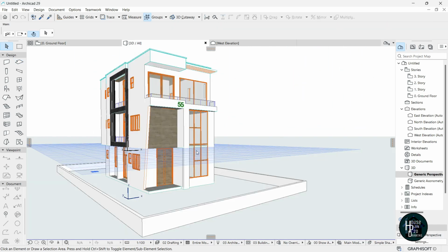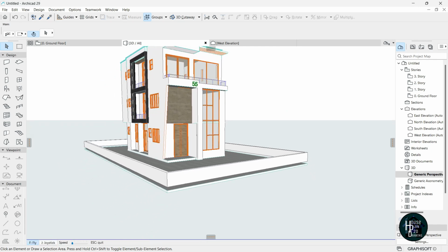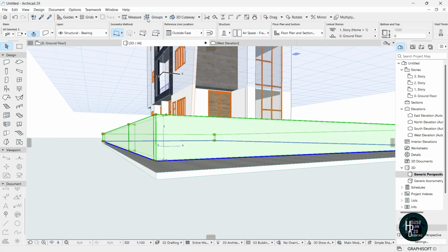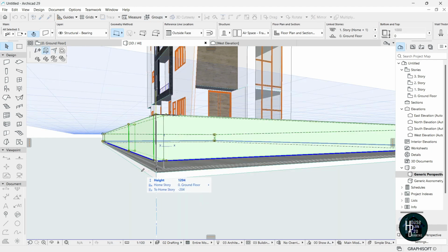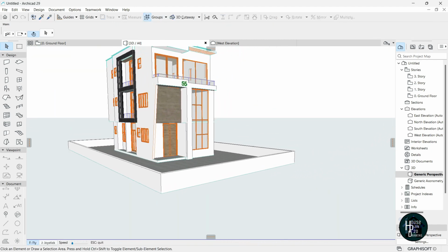Go to your 3D settings. You should have that being set up for you like that. Okay, so you want to decide to adjust this to the bottom surface. Untick your suspend groups, click this, take your suspend groups back, click on the bottom surface and click on the stretch and move it downwards like that. Okay, so that is one way to actually do this.